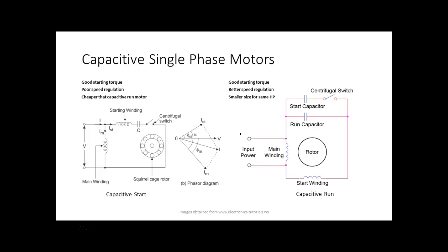A lot of your outside units are what they call a combo unit. So I've got gas heat and electric, but they'll use dual capacitors. One of them is used for your blower and one of them is used for your compressor. So they're still capacitive start motors, so don't get that confused. But you'll have to change out the whole capacitor when you do that. The one in your HVAC system outside will have 3 prongs on it. One of them will be a common, and then you'll have 2 capacitors.